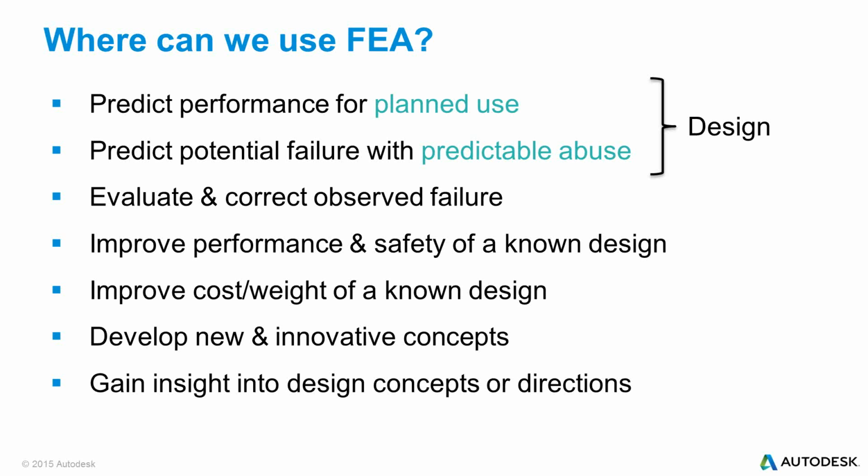Other times, you have a concept and you have no idea whether it's going to work or not, or even might work. So you could do some finite element analysis to gain some insight into the concepts, and you can find directions to it, general trends. Does making it thicker always make it worse, or does making it thicker make it better in some situations? Does it last longer if I do this, or does it not? So there's where we can use finite elements.